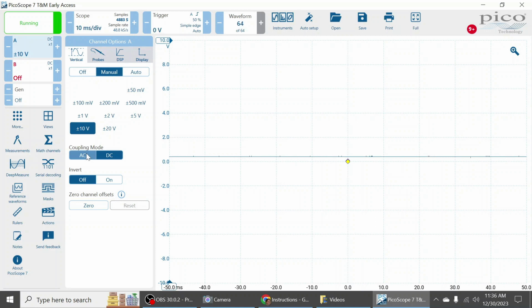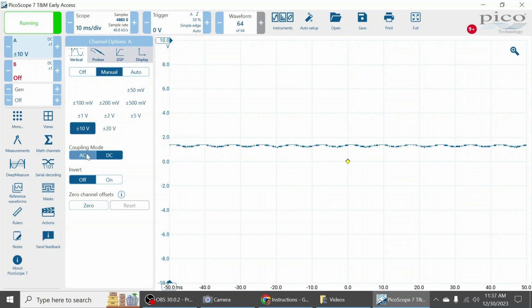The photodetector has a cool feature called gain, and that's essentially like a zoom. There are 8 settings all the way from 0 to 70 decibels. Each level roughly doubles the previous one. Right now, I have it set to no gain, so no zoom. Now I have 10 decibels, and you can see it's gone up a little bit, and we're starting to see the flicker a little bit better.